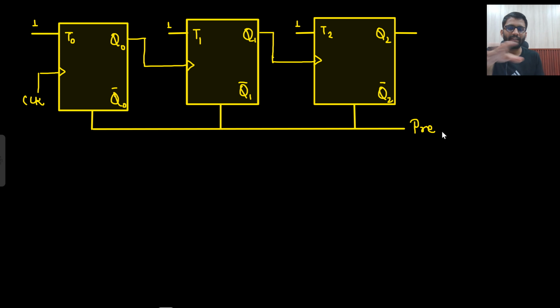Right? So first I will design a simple counter. Now I have these outputs. I wanted my 1 1 1 state to come, yes. I wanted my 1 1 0 state to come, yes. Nothing I am doing in the circuit. I was starting from 1 1 1, then I got 1 1 0. This is a down counter, right?